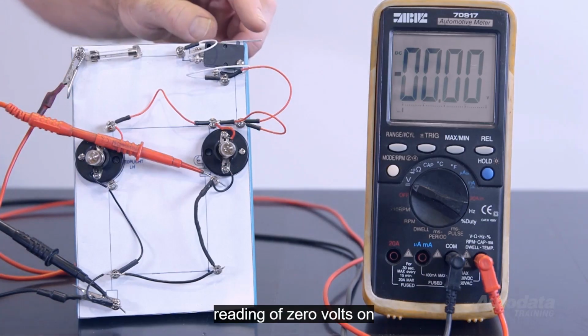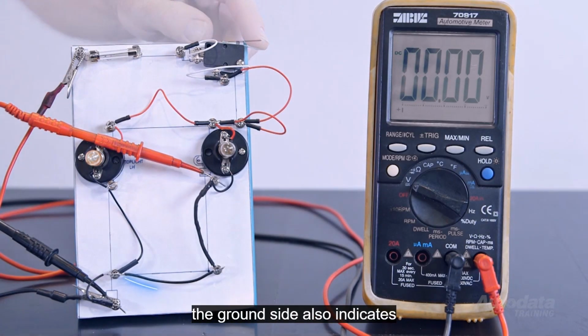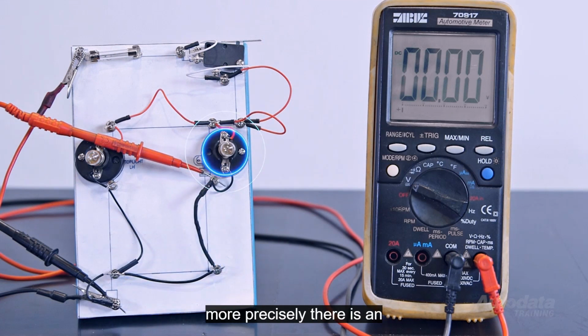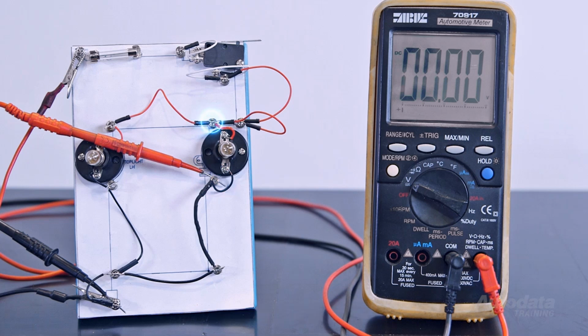A reading of 0 volts on the ground side also indicates no current flow, but this time the cause is in the load itself, or more precisely, there is an open in the section of circuit between this test point and the last one from the voltage supply side.